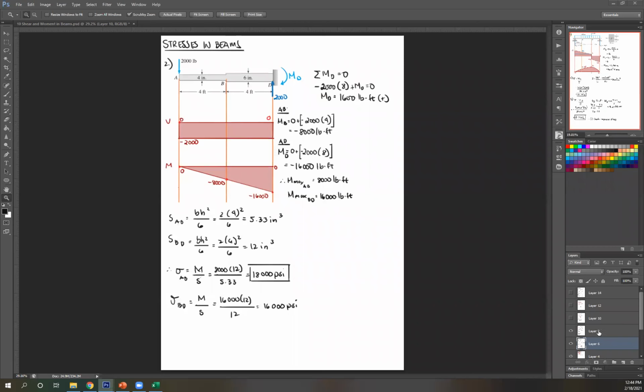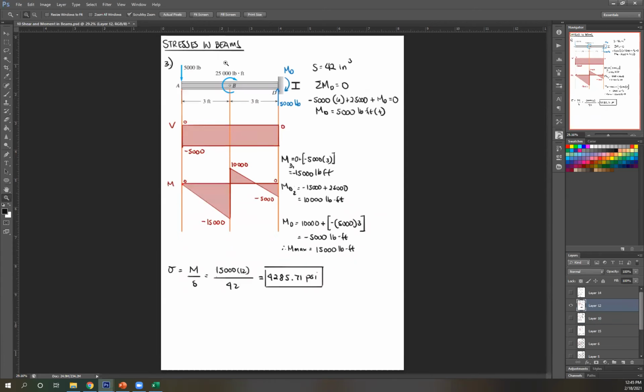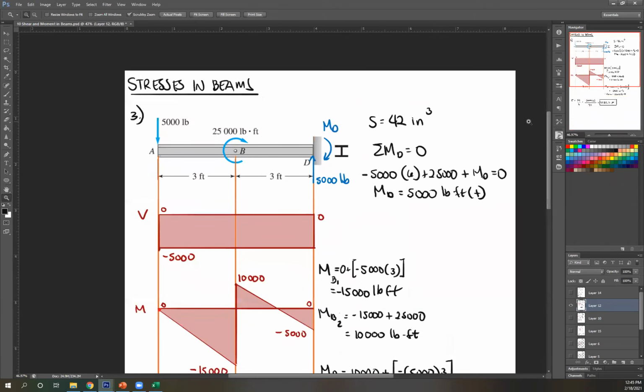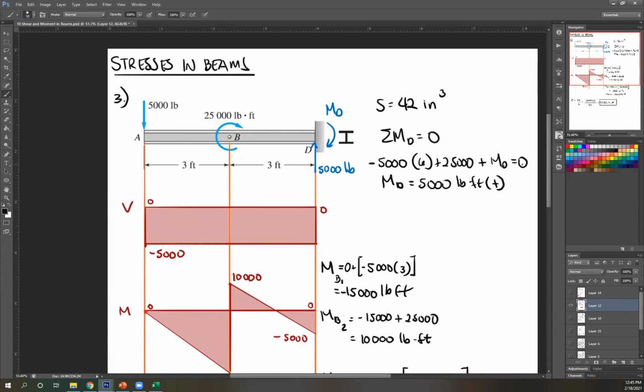As usual, what we do is create your shear moment diagram. So given S, we're going to use M over S since S is given. So now I just need to know what M is. But before that, I need to solve for reactions. This is another cantilever beam. You have a fixed end here, so there's moment and reaction. There's only one applied force. This is a couple that doesn't affect your horizontal, vertical reactions. So just one. Negative 5,000 since downward.